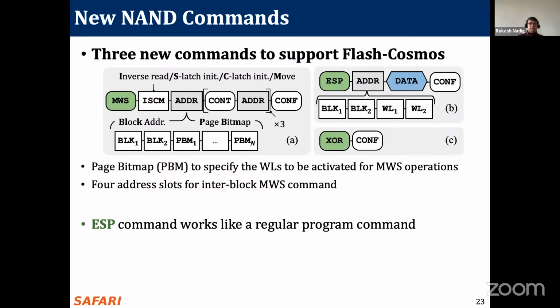Then we look at the ESP command, which works very similar to a program operation, just that it increases the number of steps in the incremental step pulse programming, and increases the voltage margin between the erased and the programmed states.